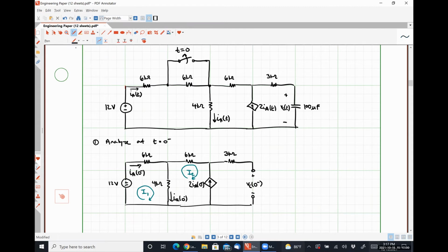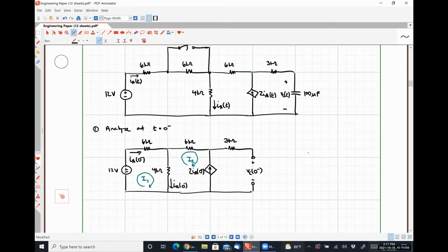All right, so I have a dependent source. So I need to, first off, express my dependent quantity, which is IA, in terms of my mesh current. So what's my equation for IA in terms of my mesh currents? IA is this guy in the top left-hand corner flowing through the 6 kilo ohm resistor, right? Might be hard to see my writing from that far away. IA is exactly equal to I1.